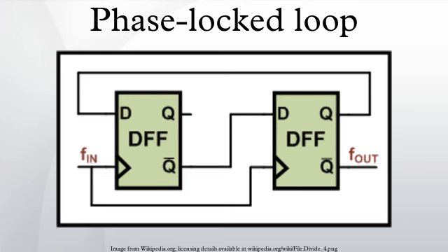Oscillator. All phase-locked loops employ an oscillator element with variable frequency capability. This can be an analog VCO either driven by analog circuitry in the case of an APLL, or driven digitally through the use of a digital-to-analog converter, as is the case for some DPLL designs. Pure digital oscillators such as a numerically controlled oscillator are used in ADPLLs.